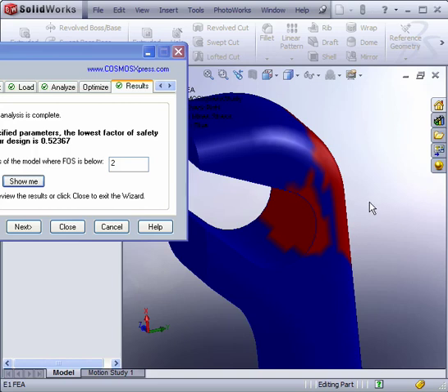If there's a small amount of blue still remaining in there, that's generally a good sign that it's not failing. It's just the surfaces are starting to almost like if you were to take a polyethylene, a clear plastic, and when you bend it you see it turn white on the edges where it's bending. That's somewhat what you might be seeing in this case, and it's not a complete failure.